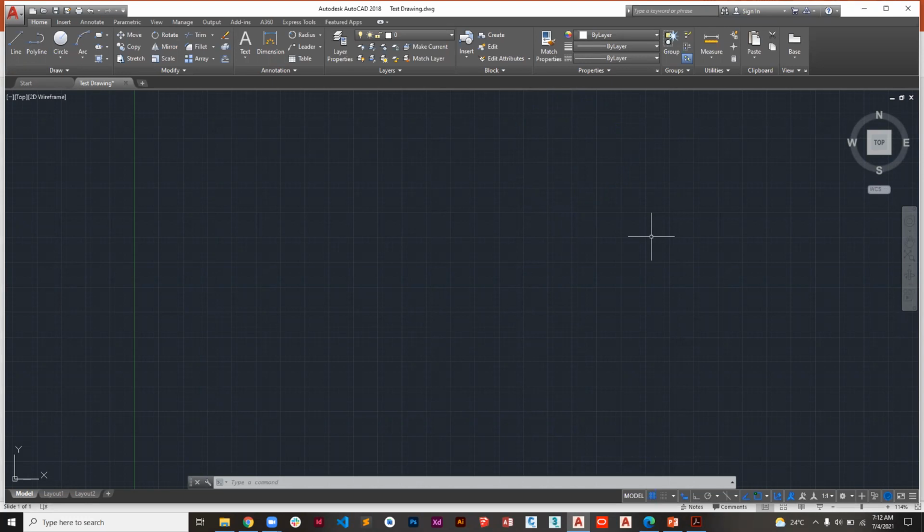For example, you want to have an option of changing the contractor, changing the consultant, or any other value. You want to make something dynamic that you can easily change. That's where the block attributes come in. So in order to use the block attributes, we must first make a block. Block attributes are mostly used in values, especially texts, not in the normal objects.